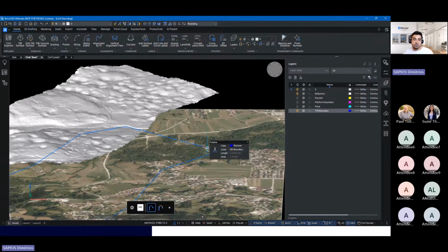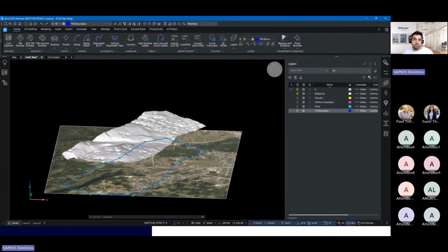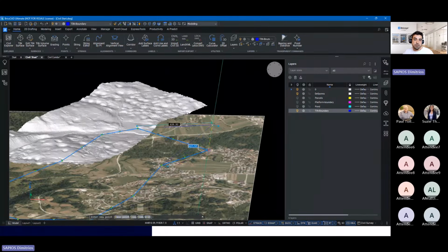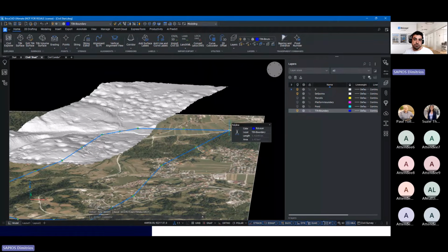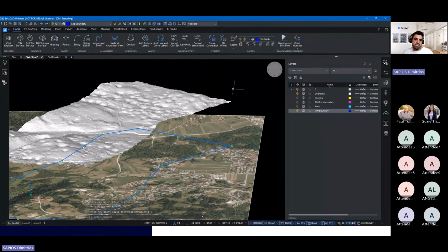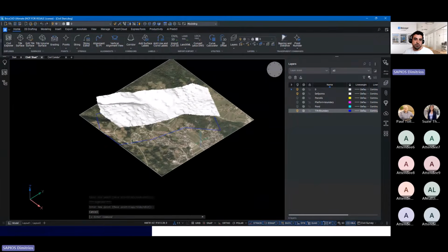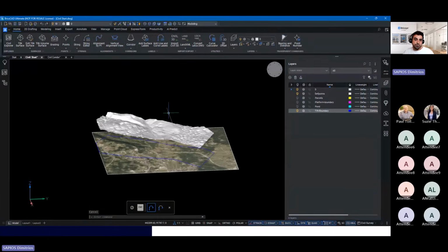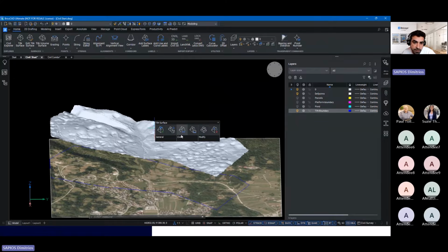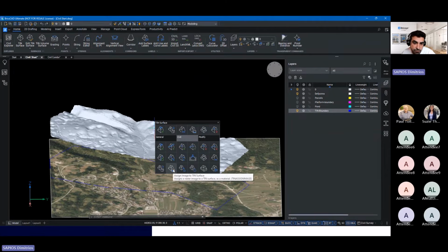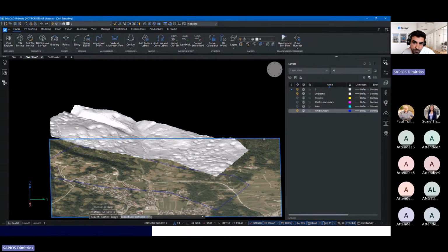And remember, this polyline can act in a dynamic way, meaning that I can change the grips, and this automatically changes the trimming of the geometry in a dynamic fashion. So the link stays there in the background. Okay, what else do we want to do? I can assign the georeferenced image to my TIN surface.